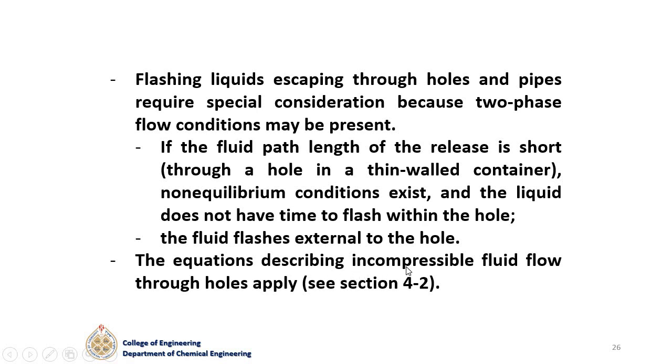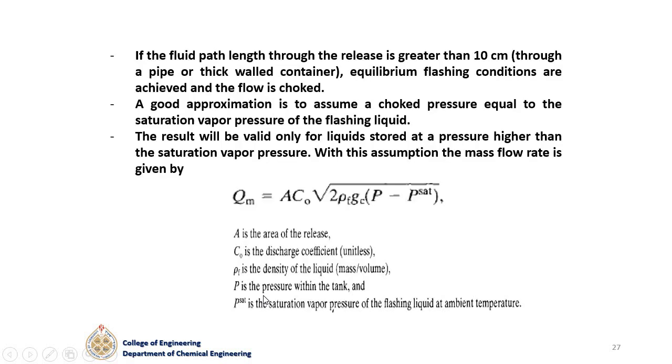The equations describing incompressible fluid flow through holes apply. I'm talking about liquid, right? Incompressible flow applies. It is this equation here. Considering some conditions: if the fluid path length is greater than 10 centimeters, I'm considering equilibrium flashing conditions, which means the flow is maximum.